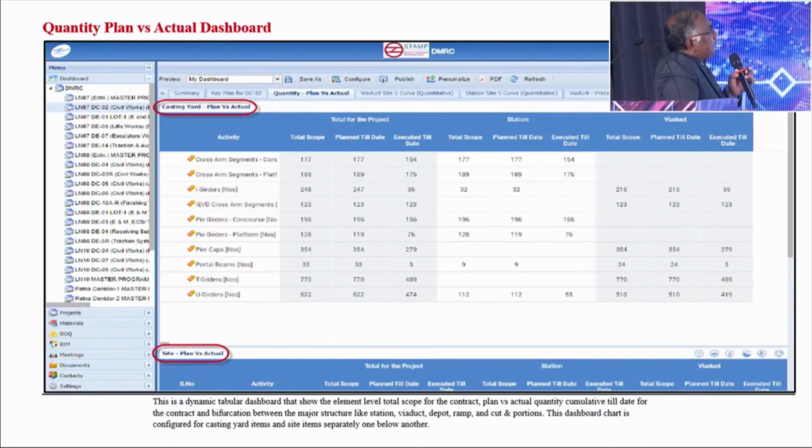You see the overall project, for example Delhi Metro, is basically a metro environment. So most of the things are planned as precast elements, which are cast at the casting yard. Even for most of the stations, we only use the pile cap and pier at the site, even including pier caps and U-girders for the viaduct, as well as in the station.